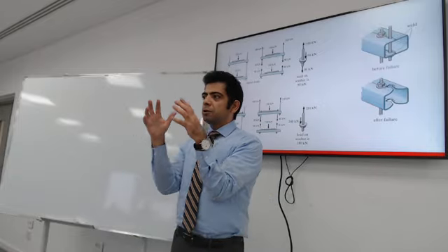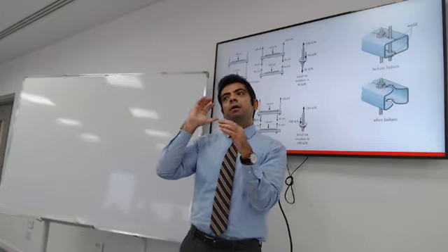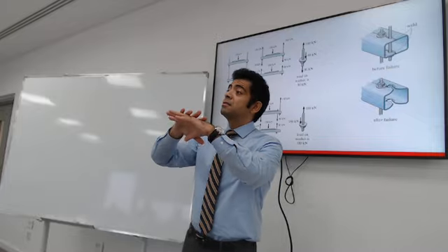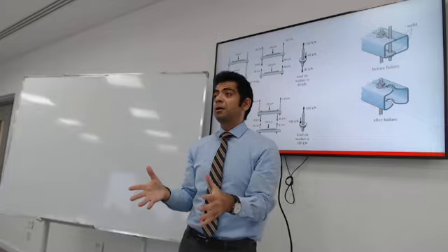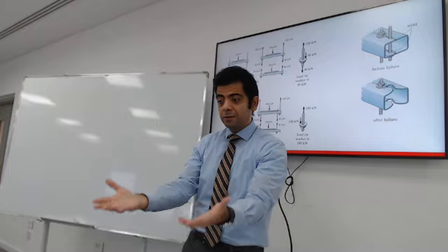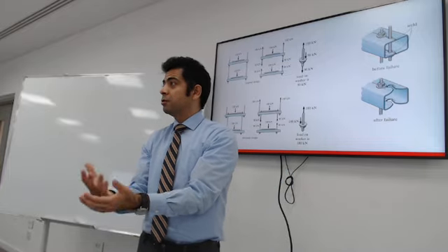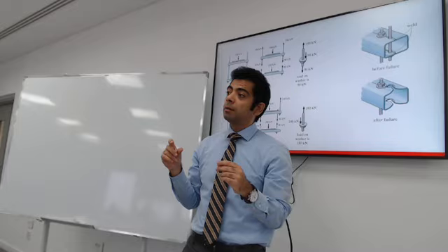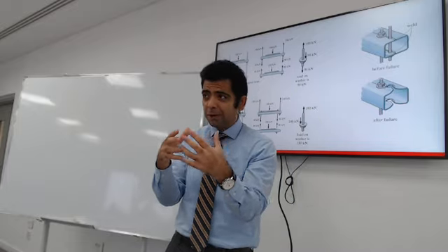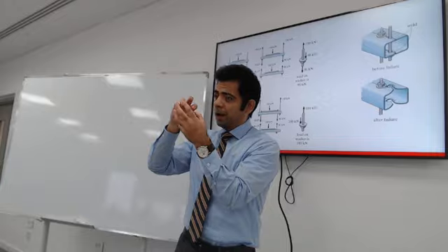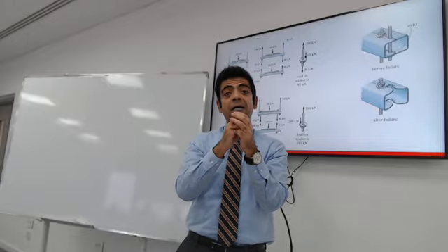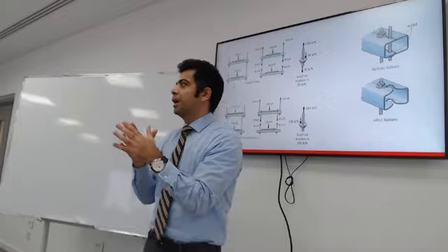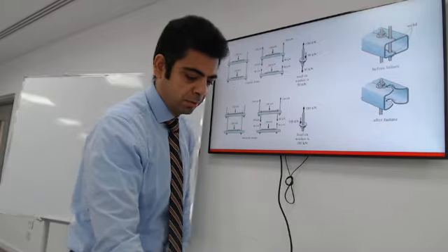When I look at a structure, I have different levels of analysis. I can analyze the stability of the entire structure. If the wind is on the structure, are there enough supports and foundation to support it? And then I zoom in a little bit and design a beam or a column. And then I can zoom in further and look at a connection. Do the bolts have too much force, so they're going to break, or are these forces within the capacity of the bolts?